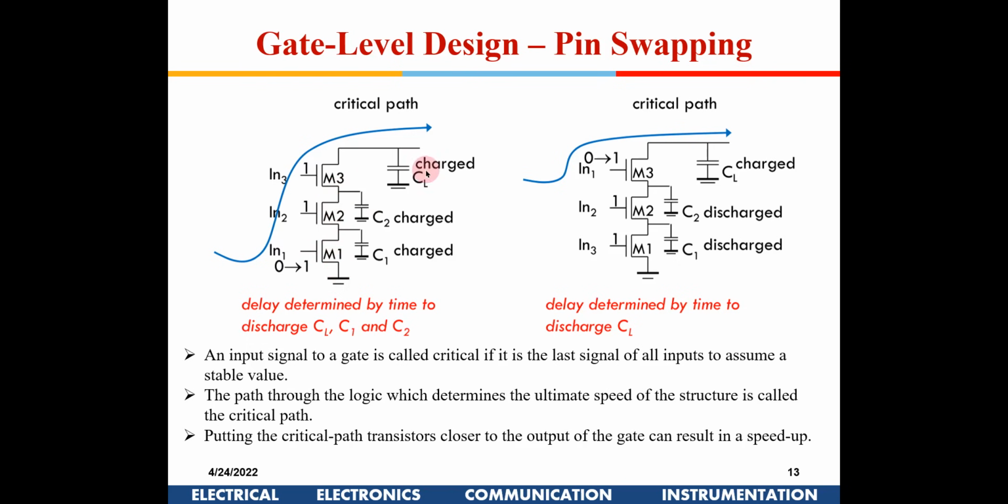So the RC delay will be 3R into C. Whereas if you reorganize these gates and put it like this, and these are generally 1, we are just talking about a specific case where the activity cycle is less, so it will be ground potential here. The moment I give a 0 here, this will get discharged directly, so there will be only one RC delay. So these gates act faster, right?